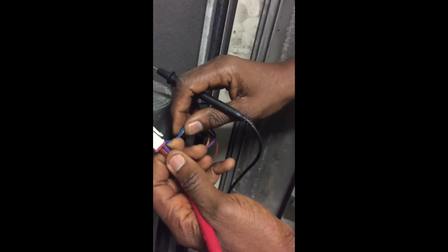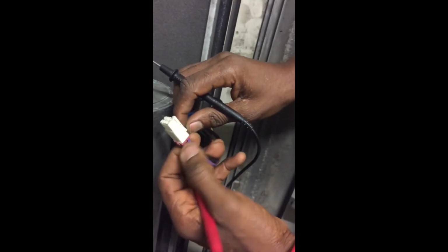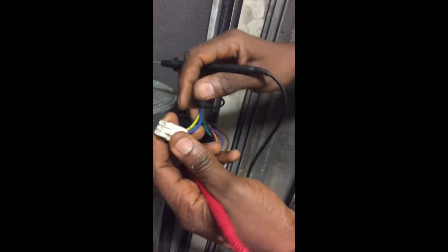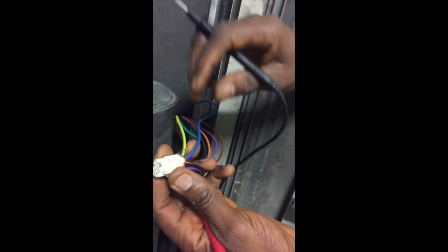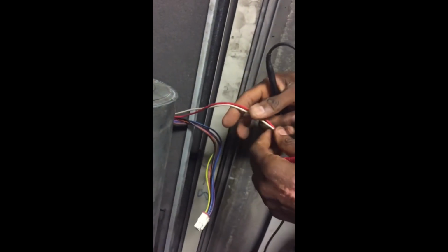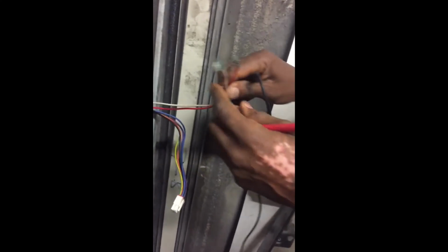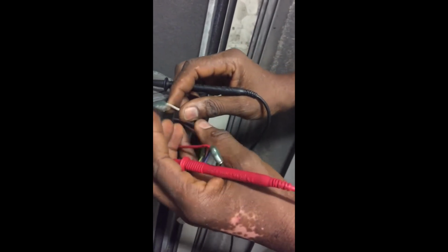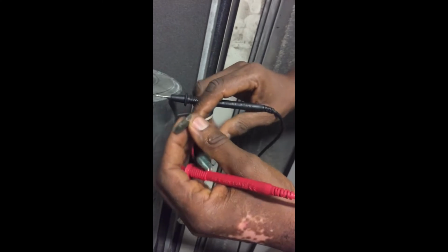So with that, we have already separated these three. Now we are left with these two, and we know that this is earth, while this is the common terminal. So with this, we are clear that we have been able to solve this problem of the speed cables. Then you have two separate cables. Obviously, these two separate cables are for power supply, and one of them goes to the run terminal while the other one goes to the start terminal.